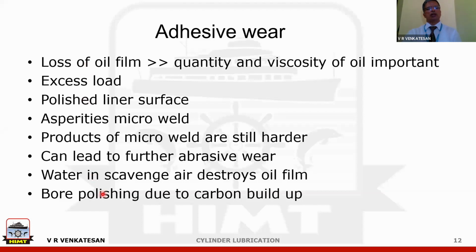So, putting all these points together, this cannot be avoided. High load on the liner and the piston ring cannot be avoided. Oil film getting reduced because of movement of the piston at TDC and BDC cannot be avoided. So there is a certain amount of adhesive wear which is likely to take place. So it's a question of controlling it.